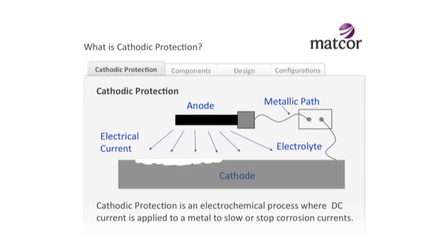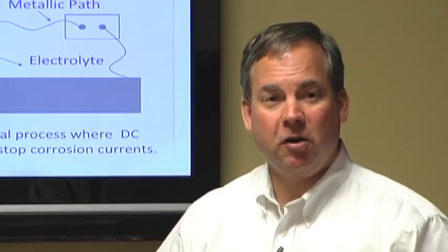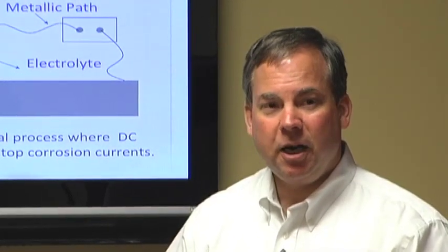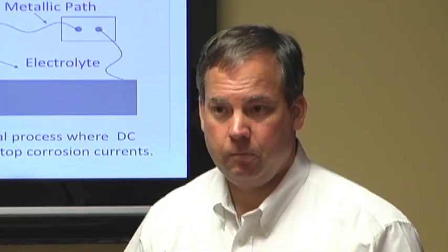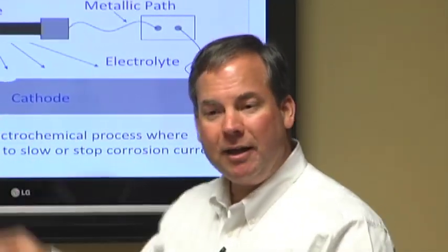Okay? One other comment here. If the structure is in such bad condition that it's mostly rust and very little meat left, very little solid metal, and you put cathodic protection on it, it could still fail. Okay? So if somebody were to come to us and say, I've got this above ground storage tank and I'm worried about my tank bottom that's in contact with soil and I'm worried about the corrosion of that tank bottom and the tank leaking, very common application for cathodic protection, and you talk to them and you find out that that tank's 22 years old and that they did a survey of the floor of the tank and they found that it got 80-90% corrosion, putting CP on it probably won't keep it from leaking. In fact, it might actually encourage leaking because what does happen is as you flow current onto there, that rust particles will start to be pushed away a little bit, and now all you've got left is nothing but a real thin piece of metal maybe.